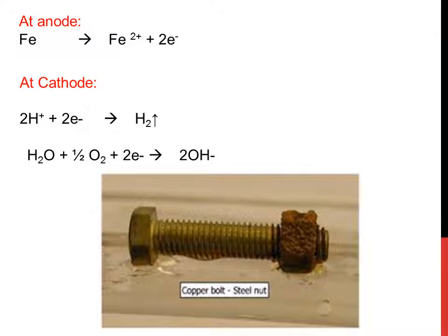This shows the concept of a smaller anodic area and a larger cathodic area. The metal or alloy placed at the top of the galvanic series has undergone rapid corrosion and acts as the anode, compared to the metal placed at the bottom of the galvanic series with higher electrode potential.